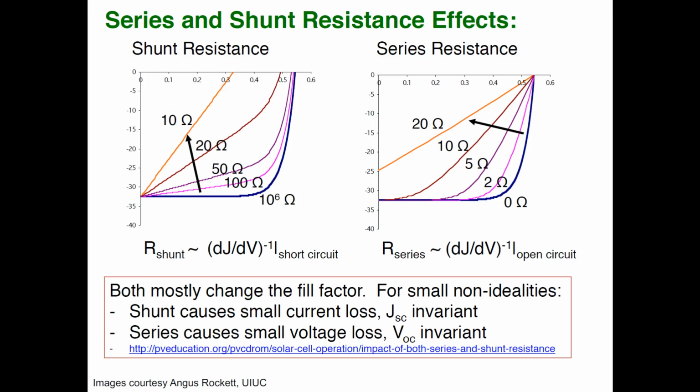Now one thing to remember here is that this again varies from material to material. So you can't really have a single cutoff point that is the same for all the materials. It will typically vary, and based on that, you will really have to choose your series resistance, or how you make the front as well as the back contacts.